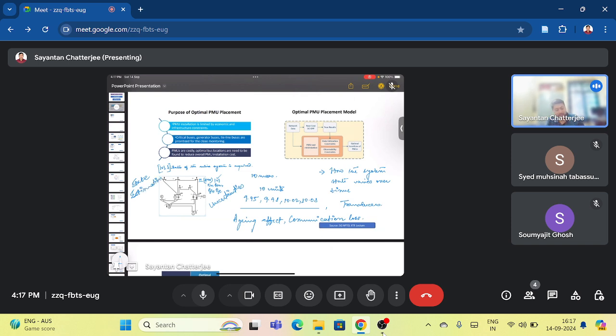And why is it called state estimation? We could have directly written the states that we can find from the metering equipment. The problem is that what the metering equipment delivers are not directly the states, or if they do directly deliver the states, as in the case of PMUs, they still contain some of the uncertainties that I have discussed here.